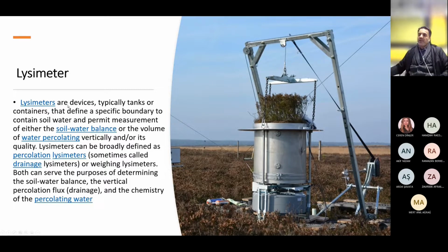Lysimeters are devices, typically tanks like these, or containers that define a specific boundary to contain soil water and permit measurement of either the soil-water balance or the volume of water that percolates vertically and/or its quality. Lysimeters can be broadly defined as percolation lysimeters, like some here, sometimes also called drainage lysimeters, or weighing lysimeters. Both can serve the purpose of determining the soil-water balance and the vertical percolation flux, drainage, and the chemistry